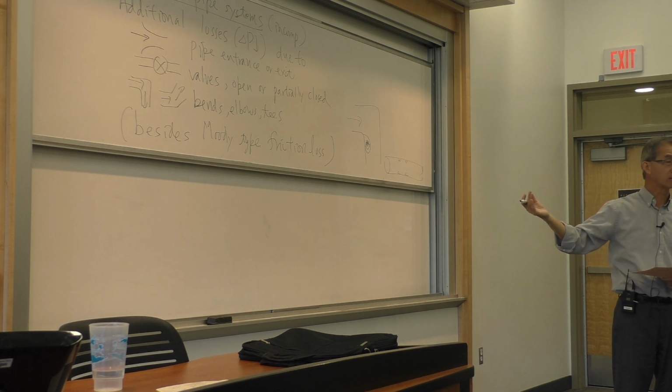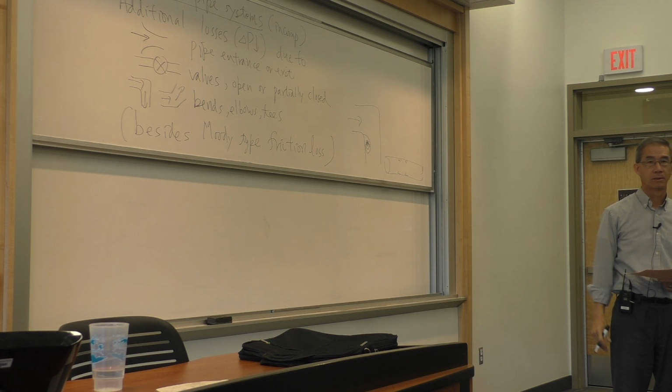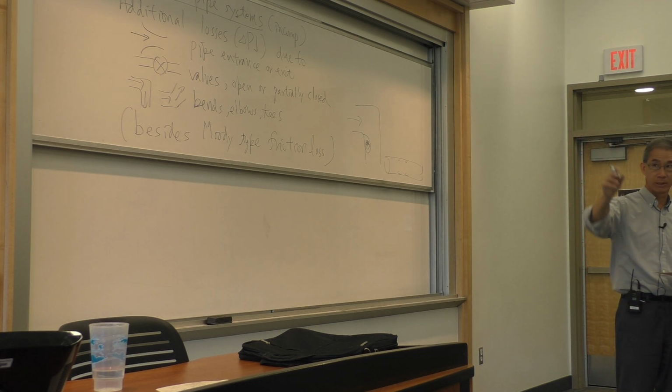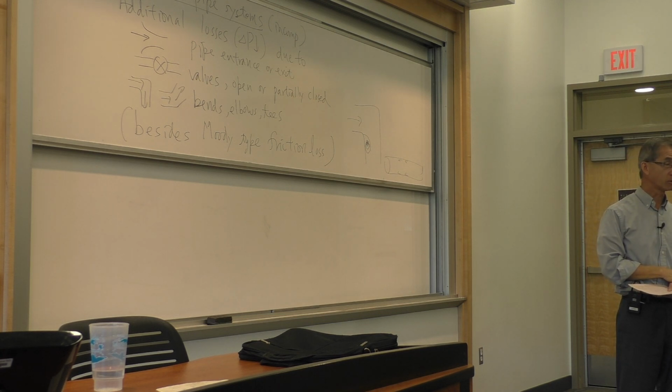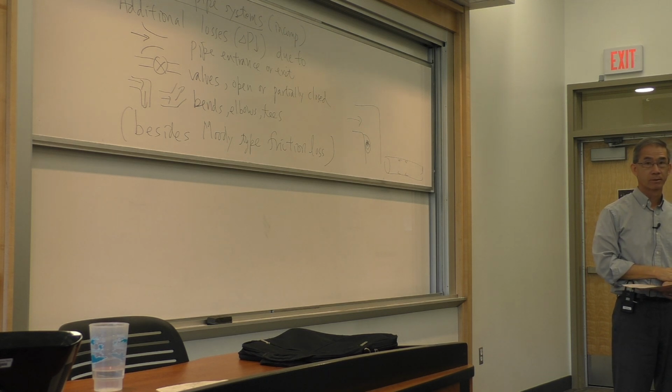But instead of saying other, we say minor. You will find by way of this example that the actual so-called minor losses for this example are greater than the Moody diagram losses by far. So the word minor is deceiving.